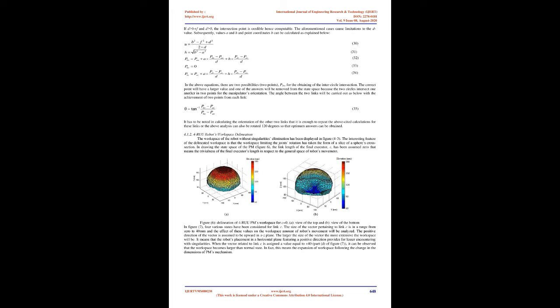4.1.1 Considerations related to workspace delineation. With the inverse kinematic analysis of the robot that determines the position of the active joints based on the final executor's position, it is now possible to compute the joints' distances. This allows the robot to specify the speed of the motors existent on the joints so that the final executor could be placed in an optimum position. There are various methods for obtaining the inverse kinematics of the robots and, as it was seen, Jacobian Matrix was obtained for the robot in the chapter before the constraints specification.